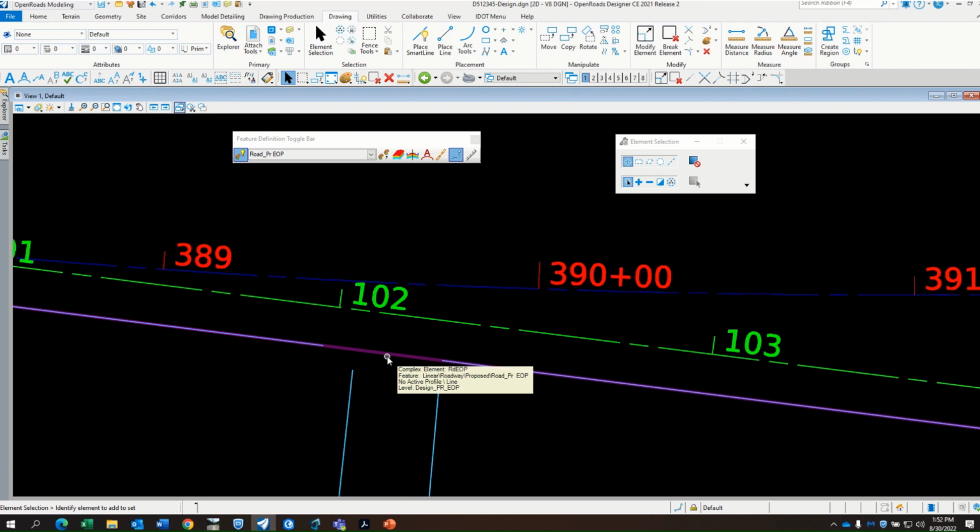Maybe when you're tying in that intersection later and you're targeting that edge of pavement, well, because you did it this way, because you went with the complete line through here, you used your MicroStation partial delete to eliminate parts of that line that are visual, and then you have, kind of on top of those lines, so to speak, as many of these little intervals as you want, and those intervals are what displays and what you see on the plan sheet.